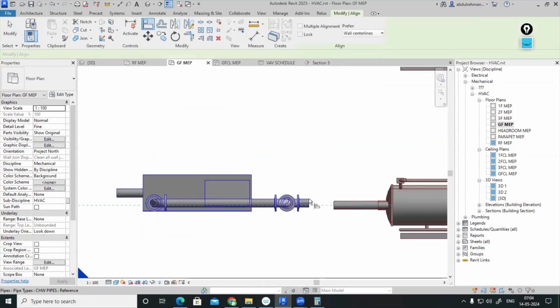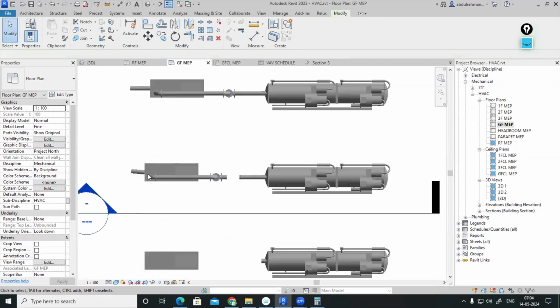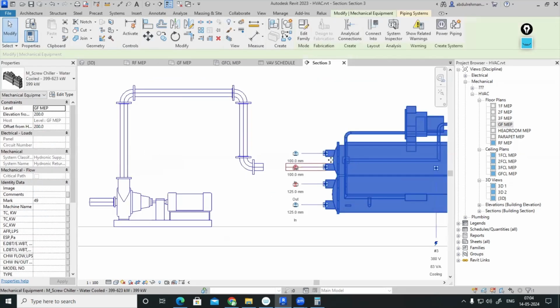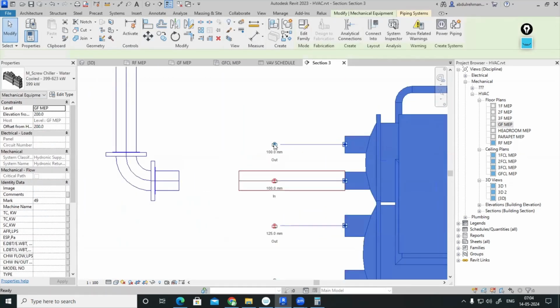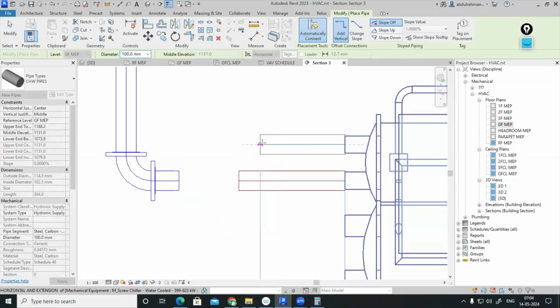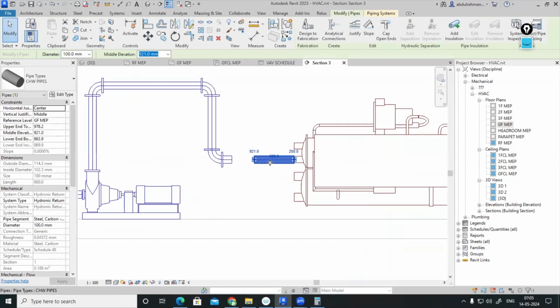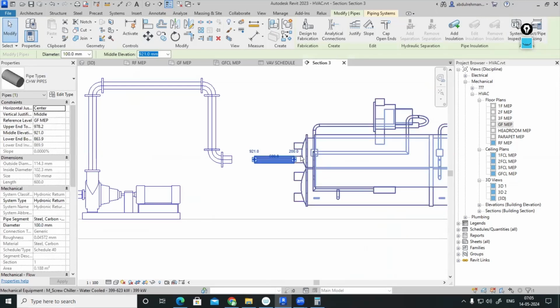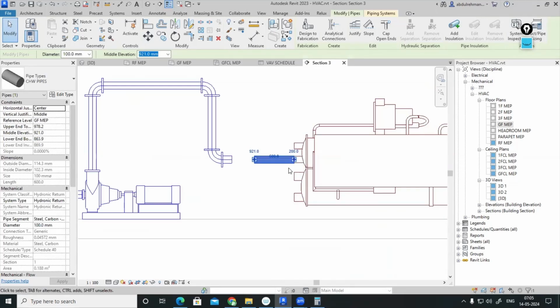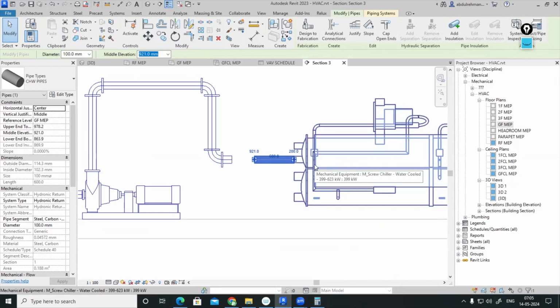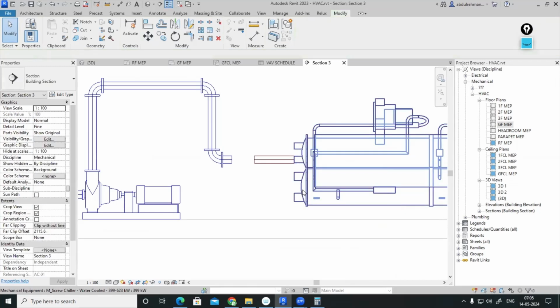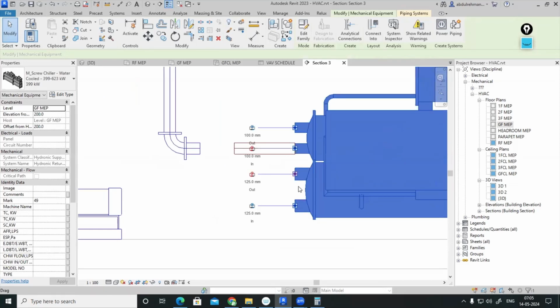When you're selecting chiller, we can see there are 4 lines. This one is 100 mm outlet. This is chilled water supply only. Secondary has to take the connection from there. This is chiller inlet. Means return only. So this hot water will be entering there, means nearly 13.8 degrees Celsius of water as per ASHRAE 90.1. And these 2 lines are cooling tower lines, so condenser water lines.